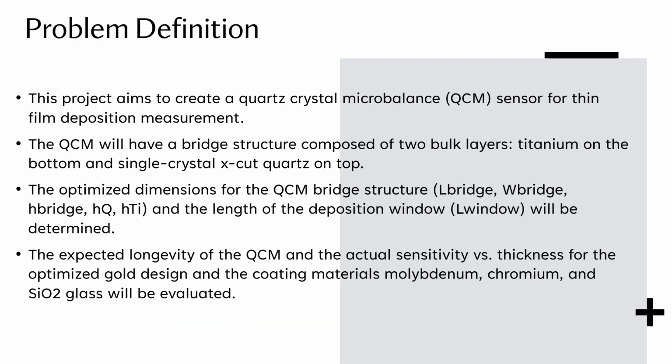This assignment aims to design a quartz crystal microbalance that can accurately measure the thickness and constituent elements of thin film deposit on a sensor. The QCM will have a bridge structure composed of titanium and single crystal X quartz with a window in the middle for film deposition. The project will optimize dimensions of the QCM bridge structure, including the length, width, and thickness, as well as thickness of each stratum.